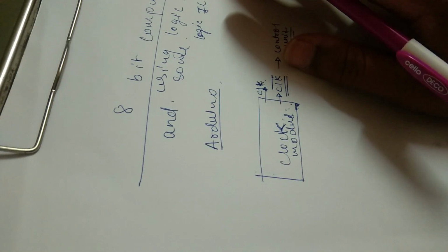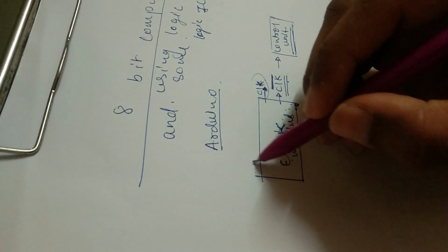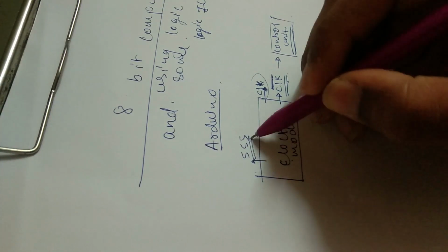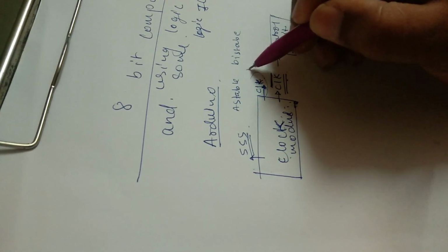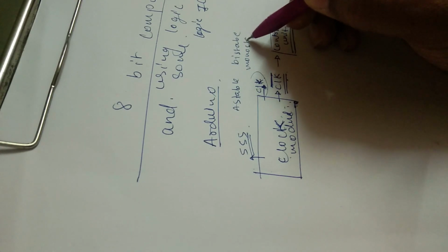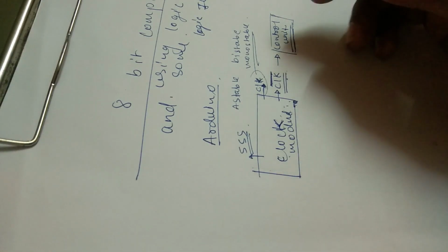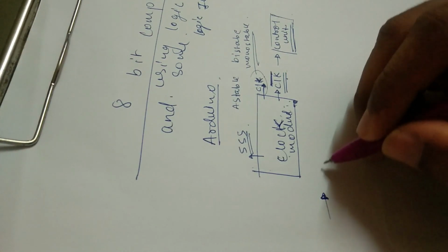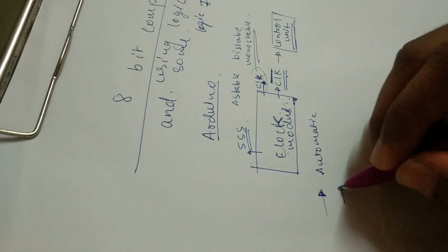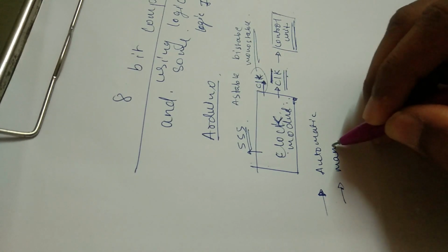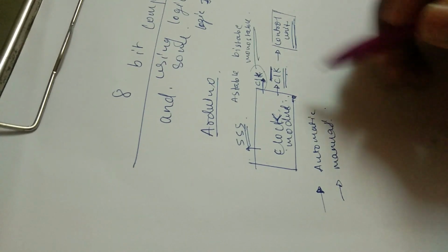Further, I was planning on using a 555 timer IC with a monostable configuration. There will be two modes in this clock module. First will be automatic and second will be manual.